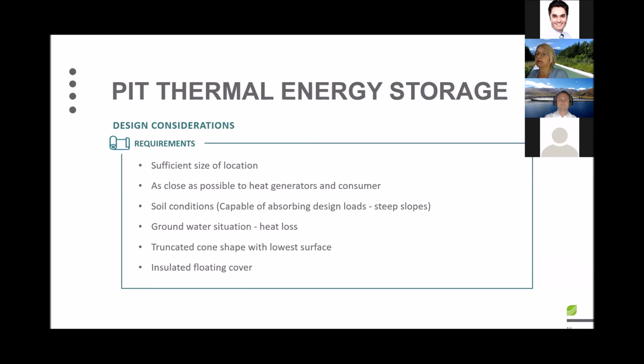A typical shape of this pit is a truncated cone, and it shall allow the lowest possible top surface in order to minimize the heat loss. And on top of this surface, there's always an insulated floating cover, which allows to keep the energy in the application.